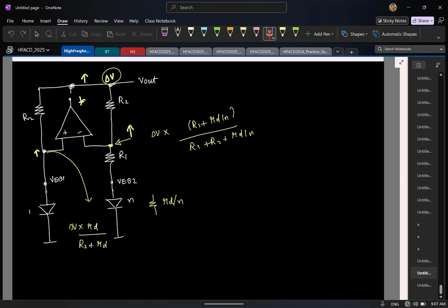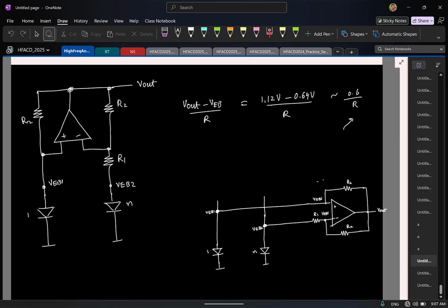And the interesting thing about this circuit is here you have both negative and positive feedback, because you have feedback from the output to both inverting and non-inverting terminal. If you have both positive and negative feedback, what should you ensure? The negative feedback dominates. Particularly at DC, there should be negative feedback around the op-amp, right? Because if there is no DC negative feedback around a high gain op-amp, the bias voltages will not be defined properly. Transistors inside will not be in saturation, and the op-amp will no longer behave like an op-amp you want. So here, if you work out, we saw that this is indeed in negative feedback. So this is fine. Let's move on from there.